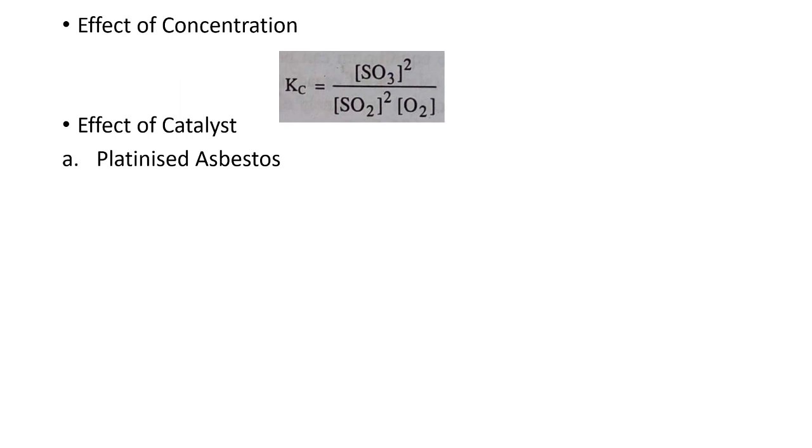Many times before in this lecture I used the word active surface. Active surface means the ability of the catalyst's surface to adsorb the gases. So slowly with extensive use, this activity goes on decreasing, and therefore the life of the catalyst becomes short.